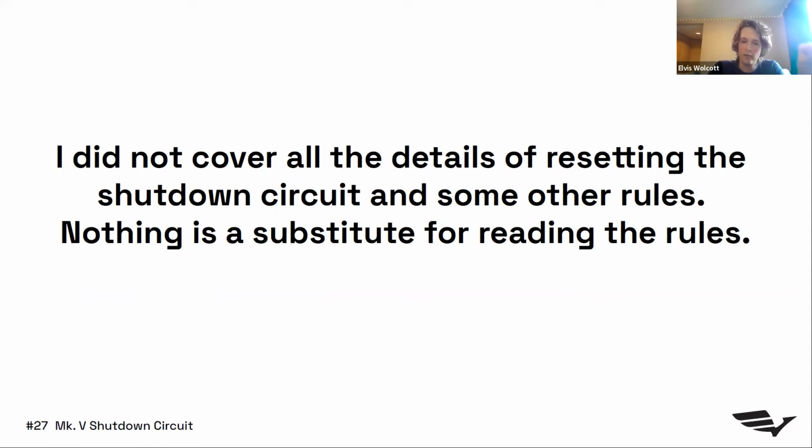One of our two AIRs closes when the shutdown circuit is complete. The other we close with the service section board, so it doesn't close automatically. That's because we don't want it closed while we're pre-charging. So if pre-charge never completes, we will never make the decision to close that second AIR. So the shutdown circuit is not the only thing that is required to close the AIRs, but it is required to close the AIRs. We can't close the AIRs without it, and it's the most likely thing to prevent them from closing. But that is a good point that, yeah, we can't continue if pre-charge isn't complete. That makes sense.